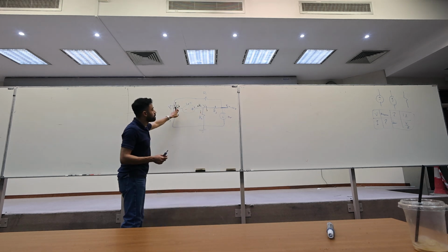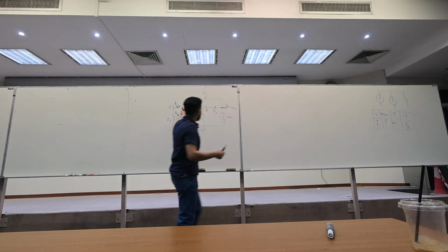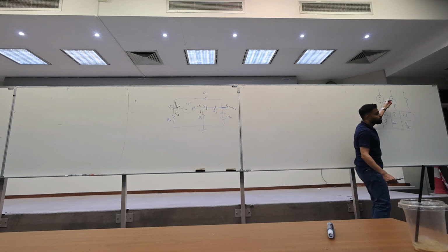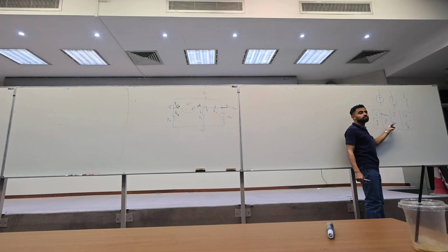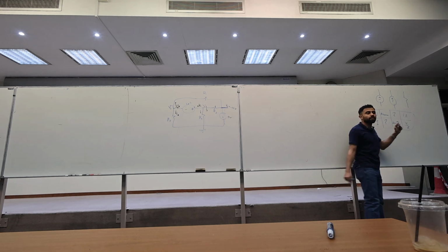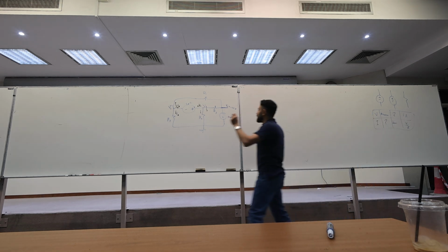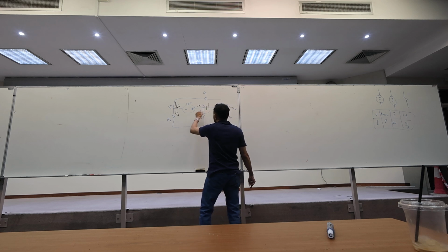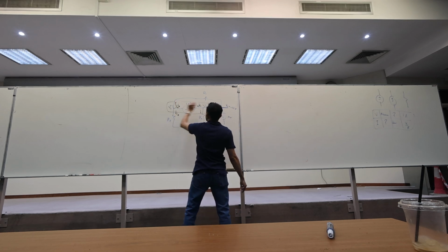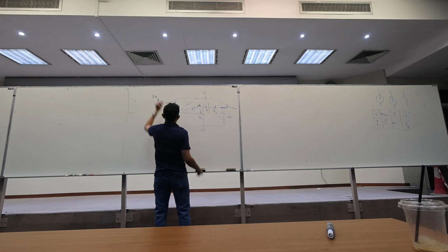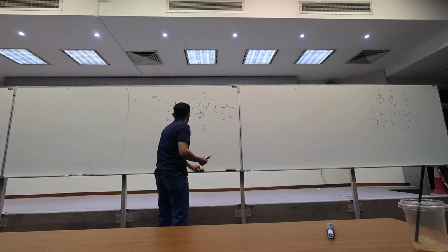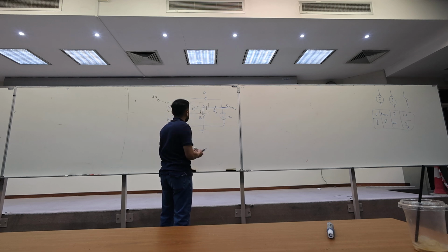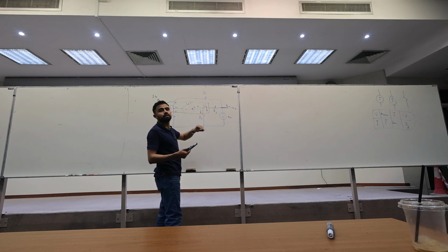But we have a problem. I cannot calculate the current that goes through the voltage source, because we don't have a resistance here. That is why we have the problem of a supernode. So the scientists called the whole V1 and V2 a supernode. They told you to forget about the currents that enter through the voltage source and look at only the currents leaving the supernode.